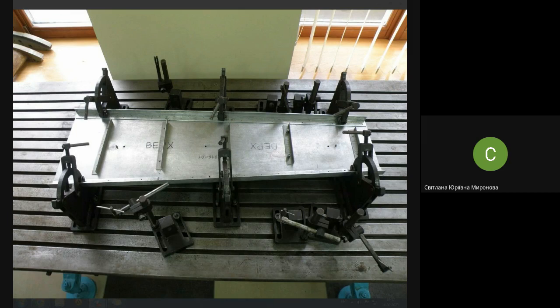But one of them determines the final accuracy. What accuracy are we interested in? We are interested in this vertical size, between the outer surface of the top cap and the outer surface of the bottom cap. This accuracy is determined by the contour locators of the jig. That is why we say it's assembling in a jig by contour. But really, we use 3 different assembly methods here.